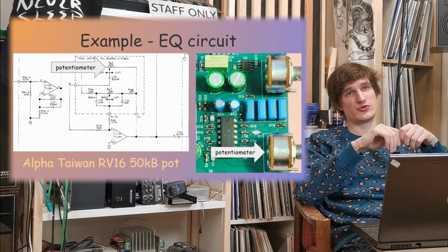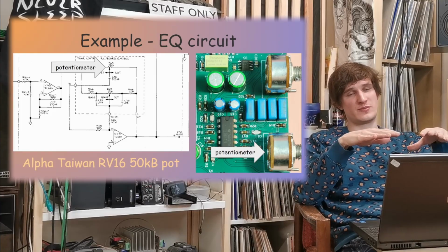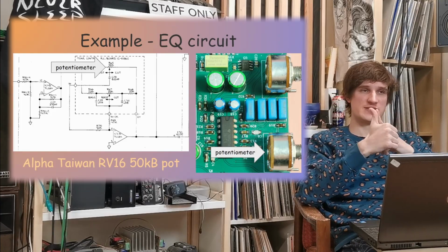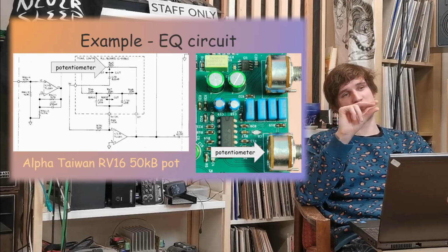The worst thing that can happen when you use lower quality potentiometers is, first, durability. After shorter use, low quality potentiometers will become scratchy. You will hear audible scratches, and you will have to replace them sooner. Also, cheaper potentiometers tend to have worse stereo channel trackability.